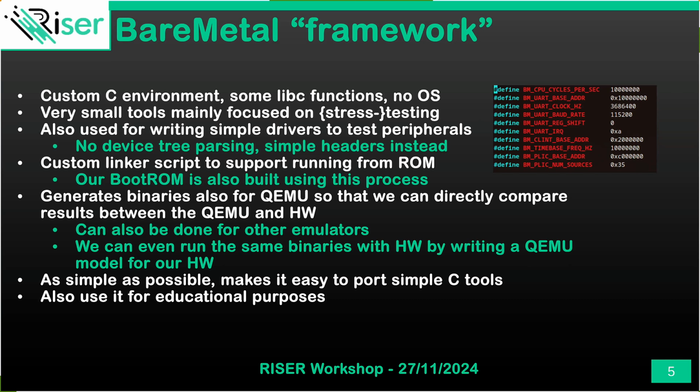So we have a small framework for running those bare metal tests. It's basically a simple environment. There's no operating system. There are some libc functions. These are very small tools, and it's not meant to be generic. It doesn't have any device tree parsing, so we have to hard code the addresses of the peripherals, the base memory, or some parameters. You can see an example on the screenshot there. For example, in order for get clock to work, we need to tell the software how many cycles the CPU does per second.